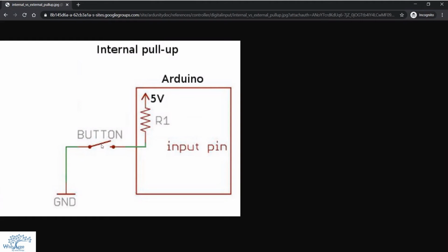In a reed switch, when we close the circuit, then this circuit will get completed and the voltage will go down to ground, because there is no resistance here, direct wiring. So this voltage will become low. So this is an important point to note. Okay.